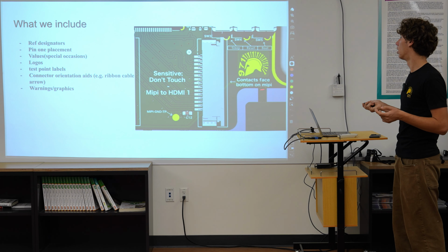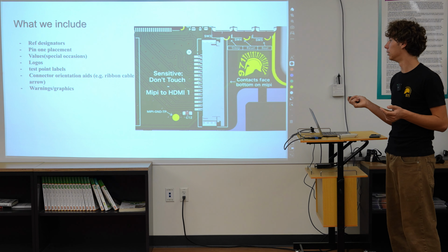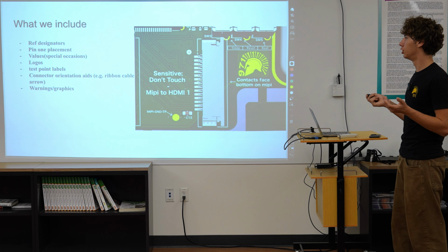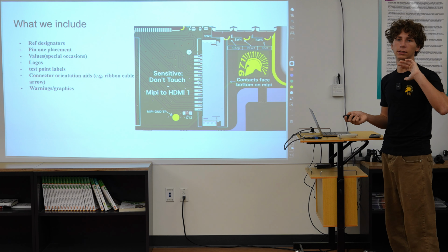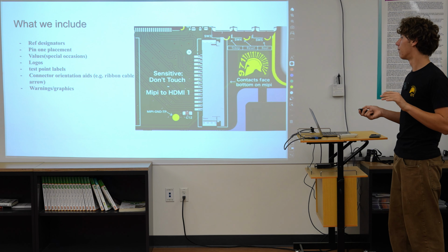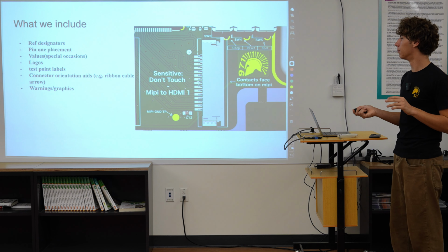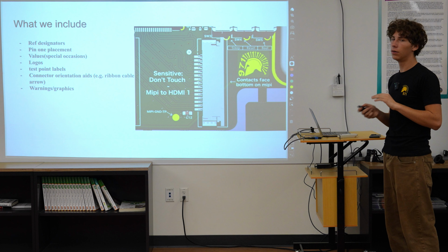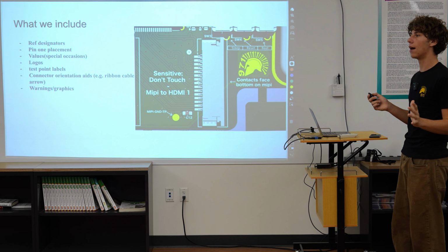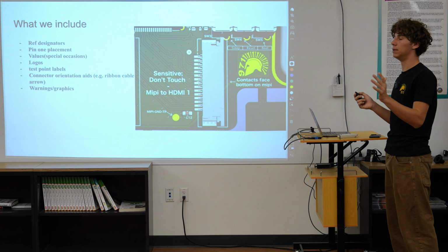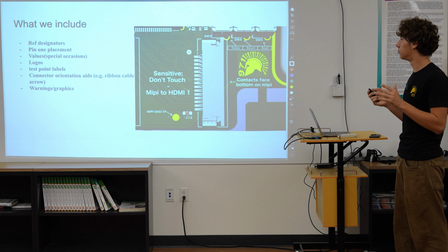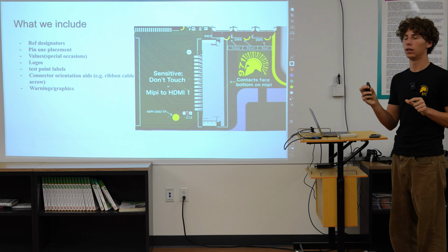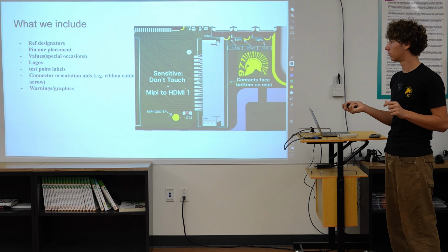Logos. So yeah, we'll put our Spartan 971 logo places. It's just cool. And then test point labels. I'll get more into test points later on. However, having a test point label is really, really impactful. All of this stuff basically goes back to not having to check the PCB every single time you want to do something. So just making your PCB very user-friendly is kind of what all of this goes back to.